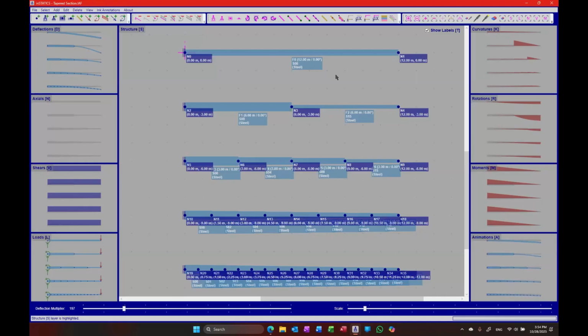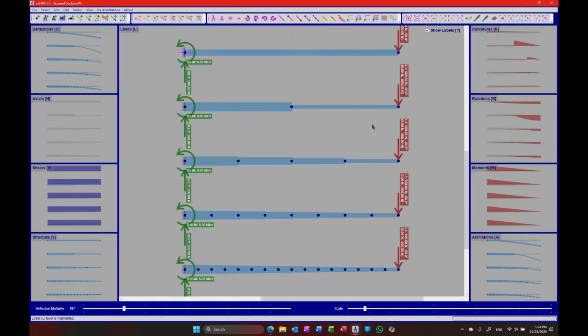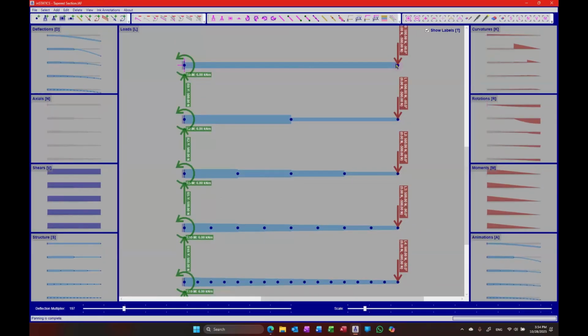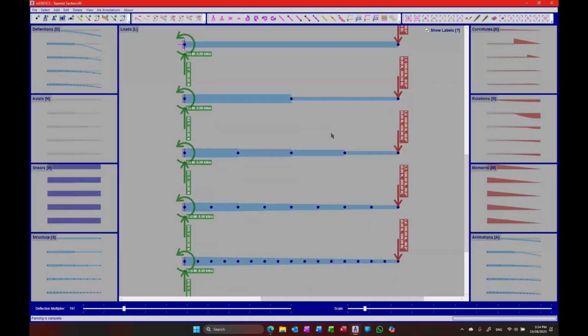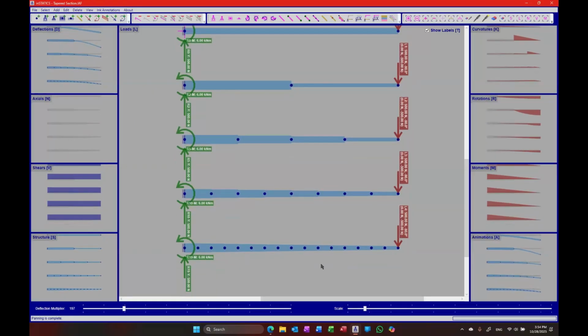But another option is to divide the section into two and use different sections in both. In this case, I used the largest section for that first half, and the smallest section for the second half. But here's the problem. You have different loading conditions every time you deal with a different thing. So it's hard to predict what is a better approximation, other than dividing the element into smaller and smaller and smaller sections.